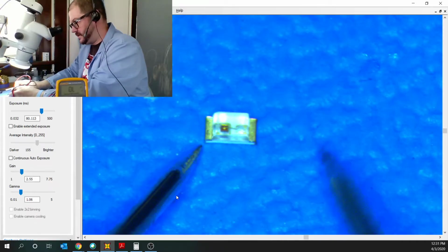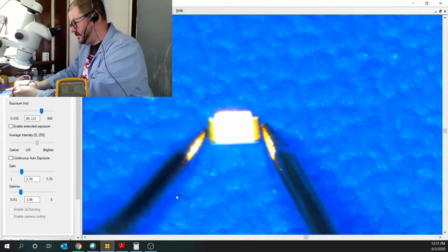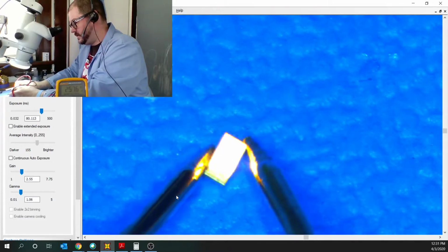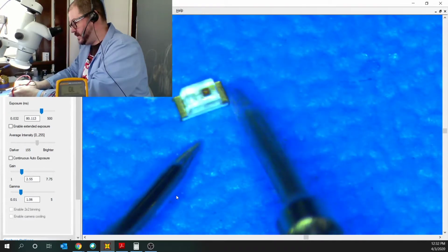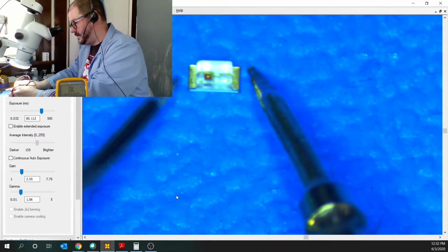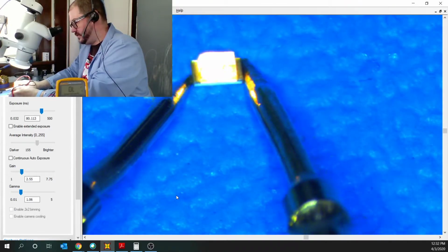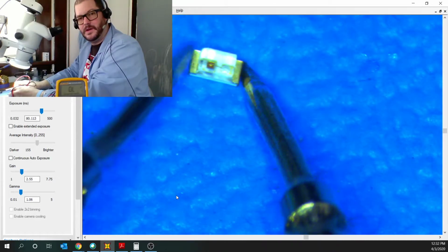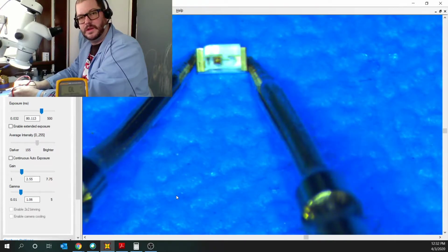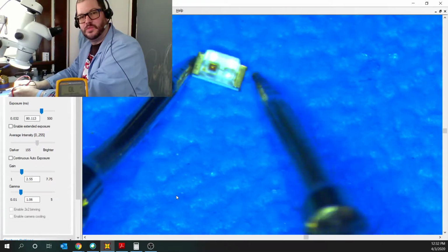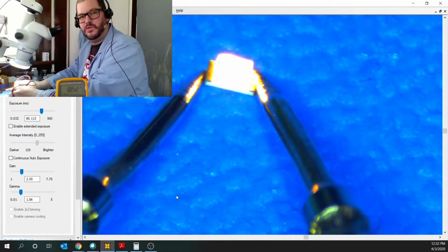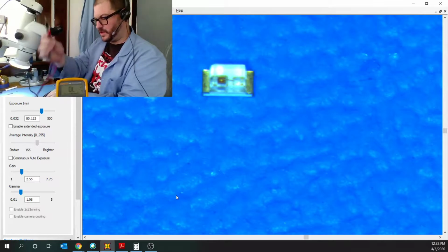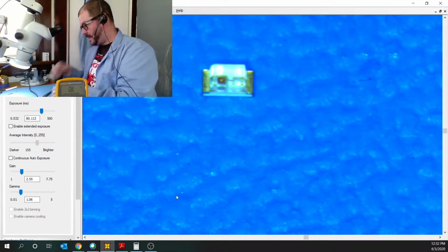So let me try that. I'm going to try to hold this as still as possible so that I can look over at the multimeter. Oh, sorry, I'm not able to get the probes in such a way. I'm trying to look at my screen right now while I'm doing this. This should be around 2 volts or something like that. 1.8 volts, yeah, 1.85 volts. That sounds about right for an amber colored LED. So the amber colored LED is here.